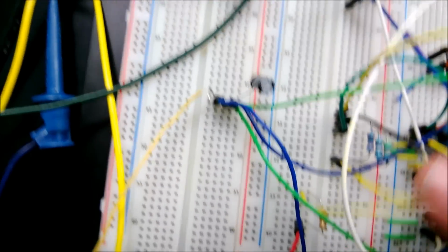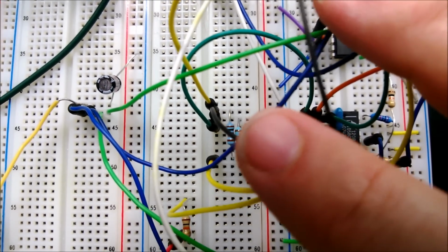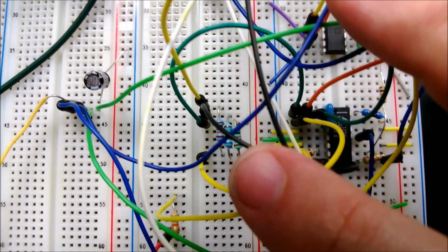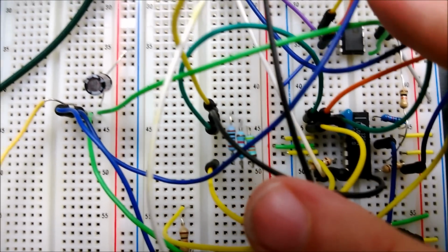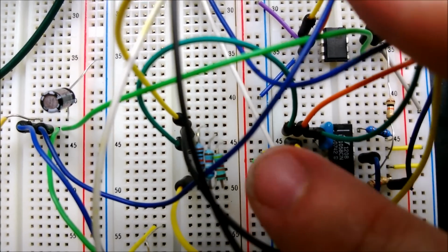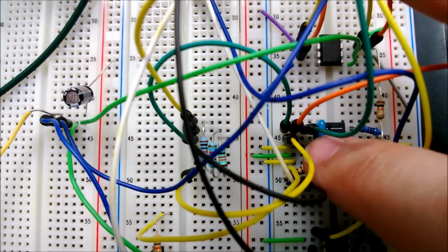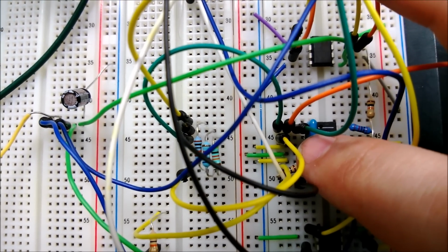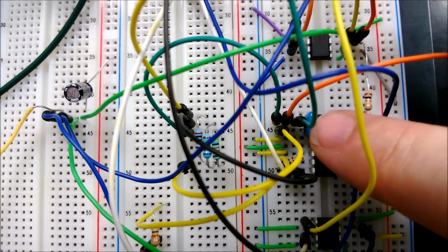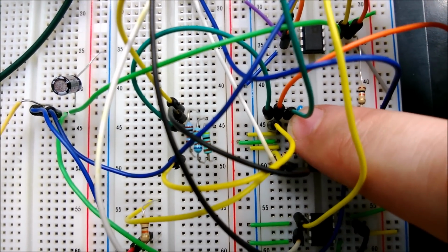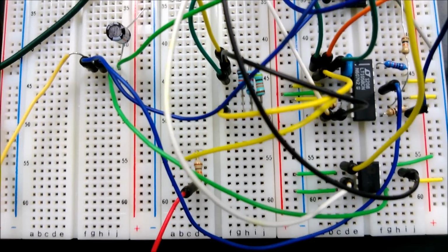Next, let's move on to the z part. We have our inputs going from left to right of minus x, minus 1, and z. Those come on down and tie in over here, and you see this capacitor that makes it into an integrating amplifier. Since Z does not need to be inverted, we just have our Z output right from here.